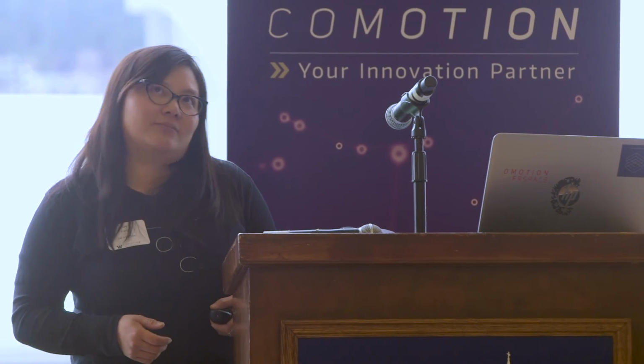Has anyone had any problems with the infills? Really high infills? I've had a problem with infills before. Yeah. Like when I'm printing a model that has a large flat surface, if the infill's low enough, then the top layer will cave in. Oh, right. Yeah. So the only fix for that is making the infill what? Higher? And then, okay, good.